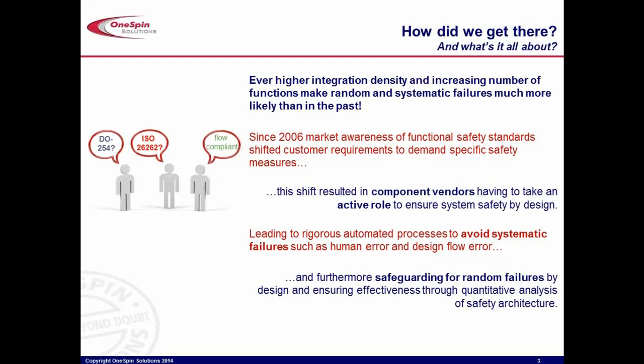On one side, improving your processes to ensure that there is less chance to introduce errors. And on the other side, introducing logic in your design that is meant to deal with failures, detect failures, possibly correct failures, and propagate information on failures to parts of the design that are supposed to deal with it, and possibly, for instance, bring your system into a safe state, so that at least nothing catastrophic happens.